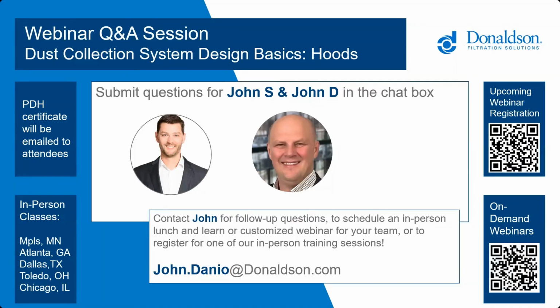Since the hood's under a negative, if you get the wrong slotted hood, you could end up with a whistling noise. But we typically don't see a lot of sound issues on the hoods. The only times are if you have, not even a slotted hood, but more of a gap in a built-up hood, you could get a whistling. But again, the solution to that would just be slowing down the air a little bit. We don't typically get sound issues from the hoods.